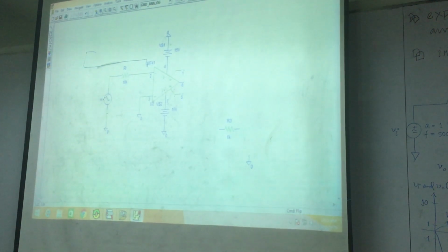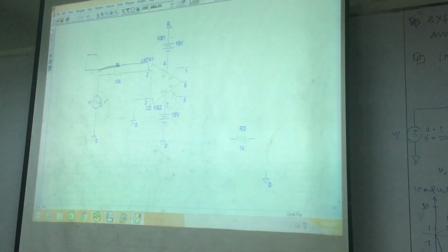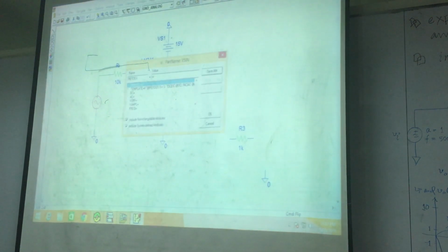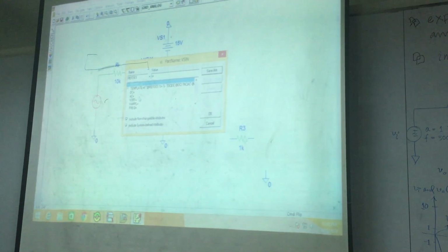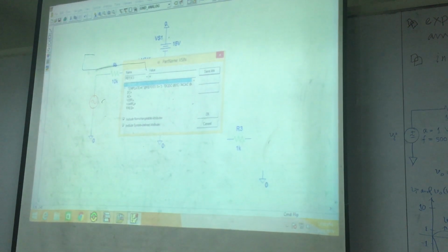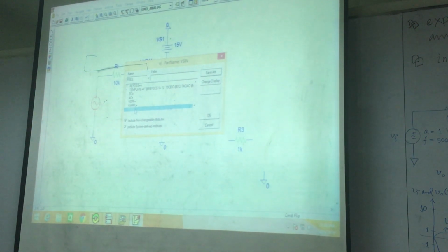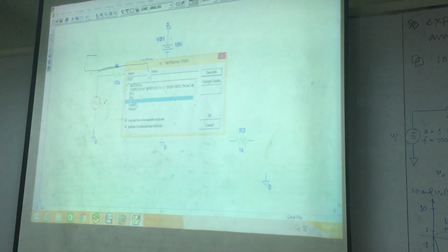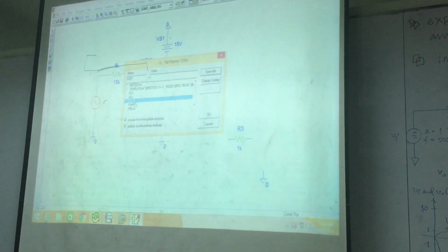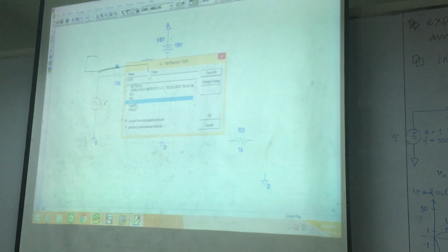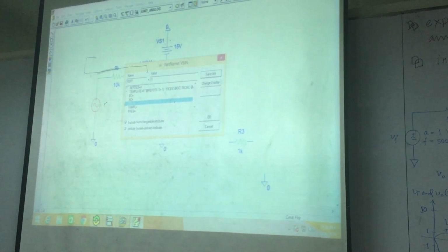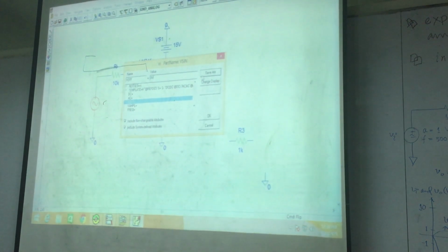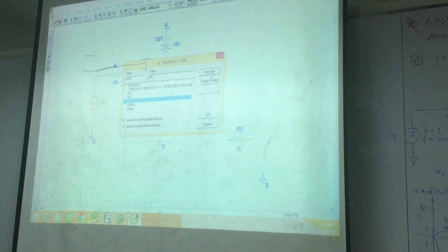Then let's get inside this source because we need to configure the amplitude and the frequency. So double click. Well, you're familiar with this, supposed to be. So 3 items to fix. Number 1, VOFF. Number 2, VAMPL. Number 3, FREQ. Okay? VOFF is nothing. Just simply keep it in mind. You need to set it to 0. Nothing else. You don't need to understand its definition. So VOFF is going to be 0 volts. Either click Save Attributes or press Enter.